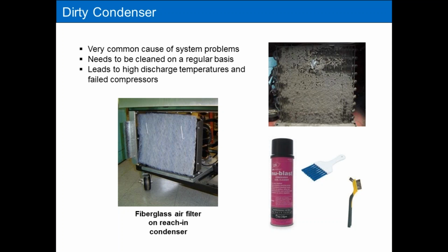You can also use some coil cleaner. They make some really good coil cleaner in a can that is rinseless. You apply it and you don't have to rinse it with water. So you can use that for these condensers, and they're pretty effective. These rinseless chemicals do work well. They even work somewhat okay on grease, depending on how impacted the grease is. But for dirt, they definitely do a good job. And grease, so-so. I use these rinseless chemicals a lot.